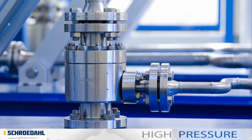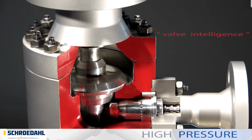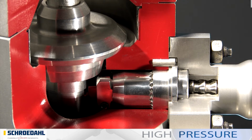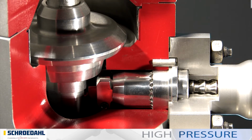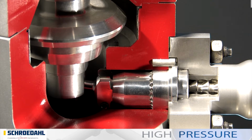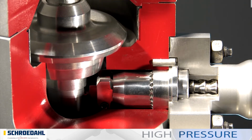Externally, the TDM is very similar to our TDL. The check valve and the bypass once again create the valve intelligence. But the conical shape on the main check valve used in the TDM, combined with the multi-stage vortex plug in the bypass, enables the TDM to handle a pressure difference 5 times greater than the TDL.